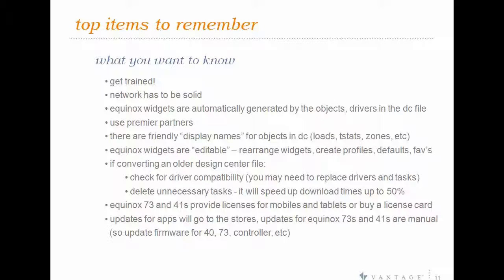So for example, if you're moving from an older project to a newer project and you use climate, you can delete the majority of those thermostat tasks, and it will dramatically increase your program times and save storage space on the controller and processing power. So it's worth doing.